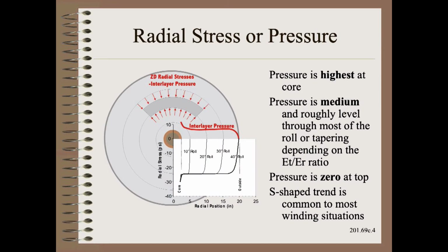So why all this roll width misbehavior? Well, it has to do with the pressure between the layers inside the roll. The pressure is high at the core, medium in the middle, and lowest, or in fact zero, at the outside. This pattern is true for all rolls ever wound of any material ever made on any winder ever made and on any winder settings or combinations of settings you could choose. In short, it is what it is, and you cannot change it.